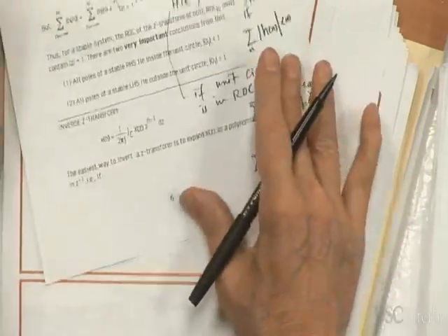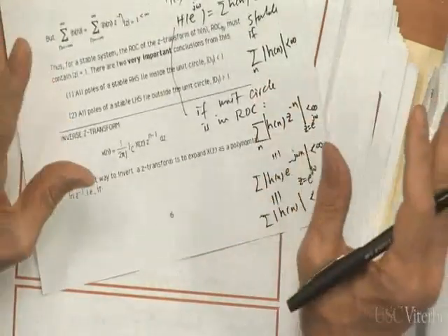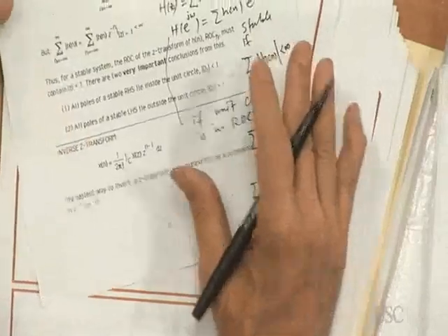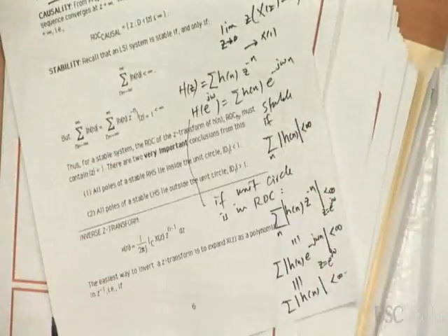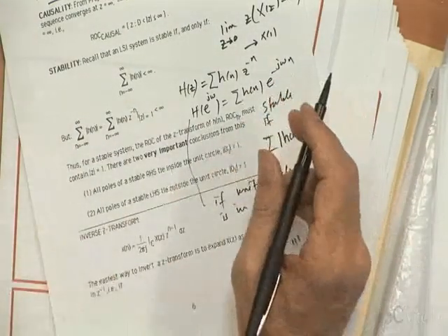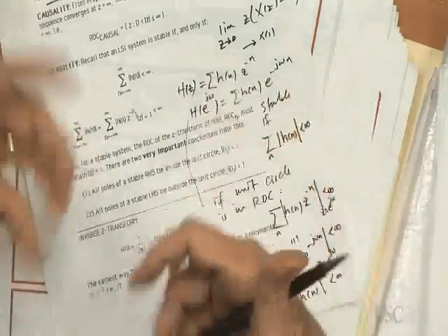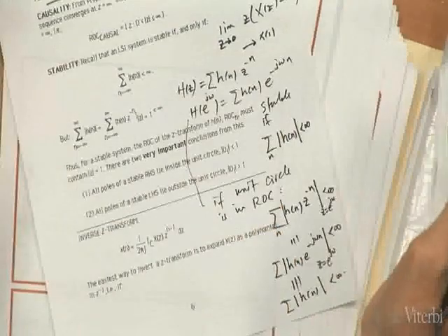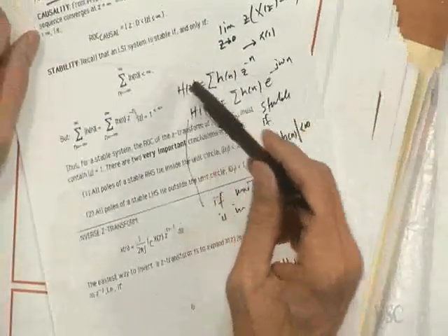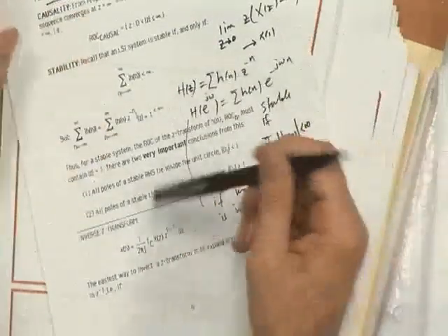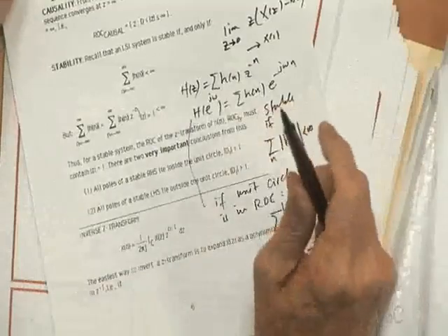What we can conclude is, if you have a z transform and you know its region of convergence, and you're curious about whether this corresponds to a stable inverse transform, then the answer is very simple. Check the region of convergence. If the region of convergence includes the unit circle, done. If it doesn't, it's not stable when you do the inverse transform.